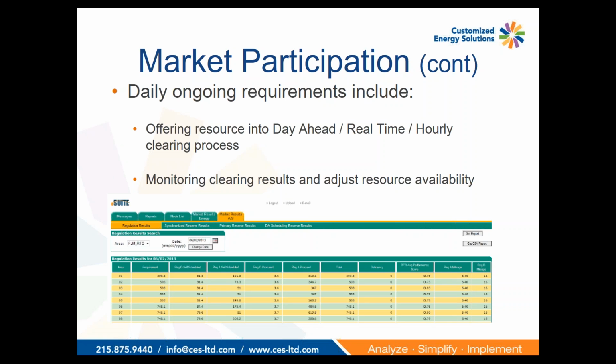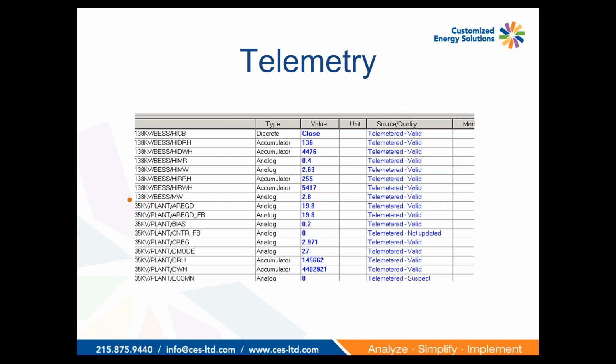For example, if an inverter goes down or a series of cells go down, you have to make sure that you're updating that information to the ISO. So typically there is some sort of 24-hour monitoring and scheduling function that's needed along with these resources. And probably a little bit hard to see on the screens there, but that is a screenshot of the PJM scheduling system where they post the results out each hour. This happens to be the public results, but they also post individual results out to each resource so that you can see how much has been assigned.